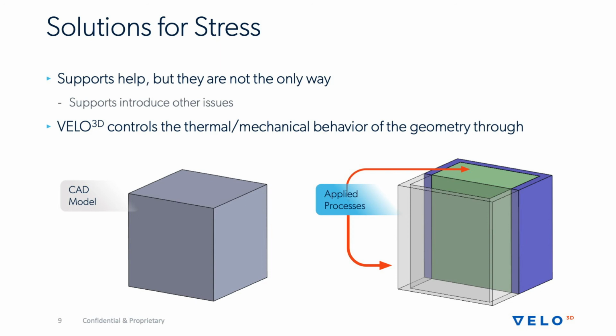The limit of the technology out there today is that the processes are applied in a fairly simplistic way. On incumbent systems, you may have a bulk fill, a skin process for, say, a vertical orientation, one for if these walls are top facing at more of a shallow angle, and one for a down-facing surface. But the issue there is the process that's optimized for, say, a 60-degree surface from horizontal.